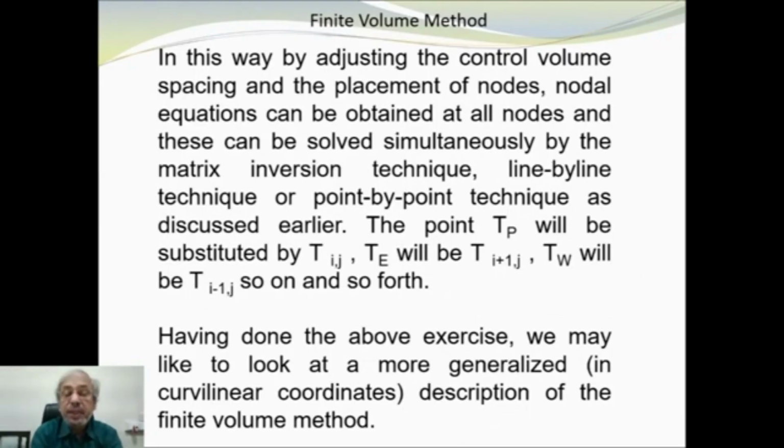But as I have mentioned in the last line, in complex geometry the grids will be curvilinear and the grid mesh will be complex. There, the same integration technique needs to be improvised. We have to see how to improve this integration technique so that the integration can be done on curved surfaces in order to balance the fluxes.